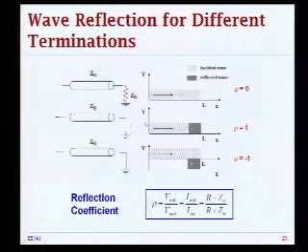In the perfectly matched case, R is equal to Z0, so the reflection coefficient is equal to 0. Basically nothing gets reflected, which is a really nice case. In the case where R is infinite, the reflection coefficient becomes 1. When R is equal to 0, the reflection coefficient is -1. So these are the three extreme cases in terms of reflection parameters that we need to analyze.